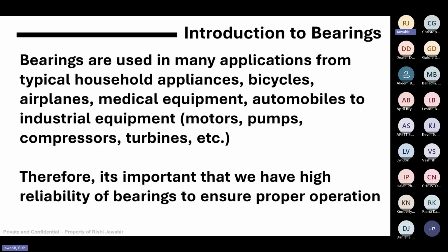Now, why is it important to have high reliability? Because reliability and safety go hand in hand. When there is a reliability issue, or equipment with a known bearing fault, it also poses a safety issue to the plant. You don't want your operators, your technicians, those doing your condition monitoring and testing, around rotating equipment that has known defects or vibration issues for any lengthy period of time.